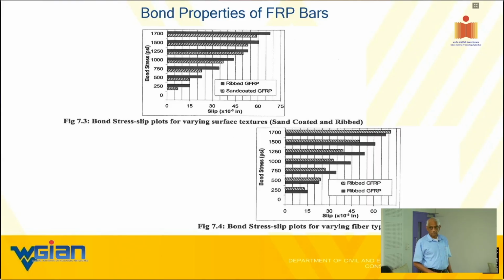So, my question is, even in the tension test, we use a similar gauge, the grip's length. If the grip length is less, and even my failure is within the gauge length, will it be permitted? Yes. As long as the failure is in the gauge length, it is permitted.